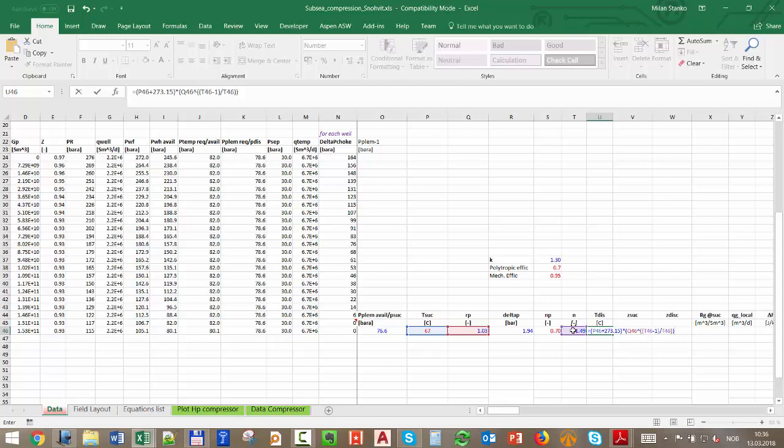So I have to subtract the 273.15. Now you obtain 69, which looks okay in terms of all the other things that I told you. Operation of the downstream pipeline looks fine, the methanol vaporization looks fine, and also the seals of the compressor. So everything seems to be fine on that point so far.